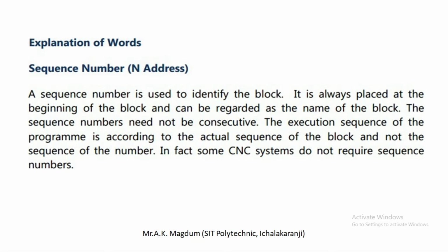If you get any error at the time of machining, how can you find that error? If you don't mention the N sequence numbers in the programming block, it is very difficult to find the block where the error actually occurs. So the block addresses or sequence numbers are very important to easily find where you are getting difficulties performing the operation on the machine itself.